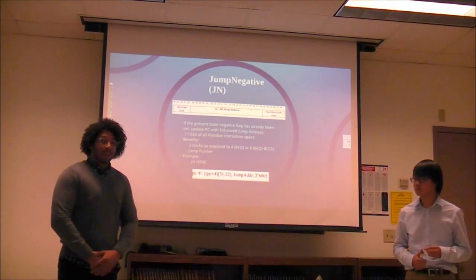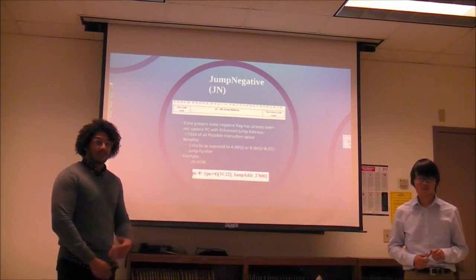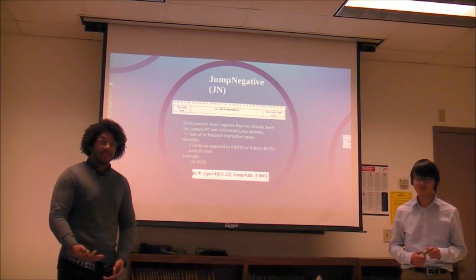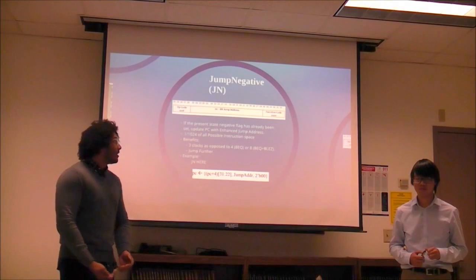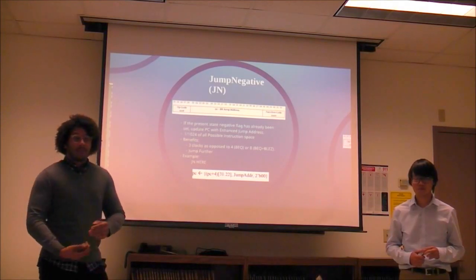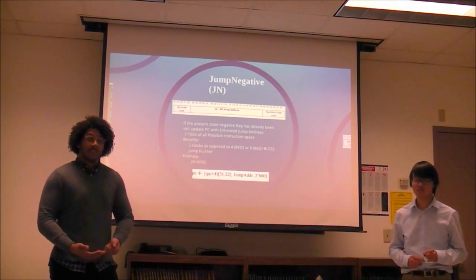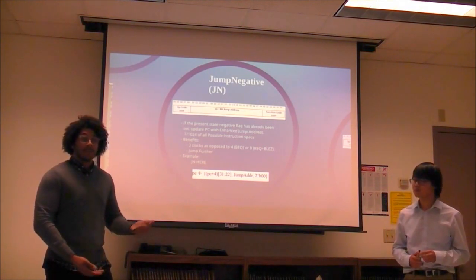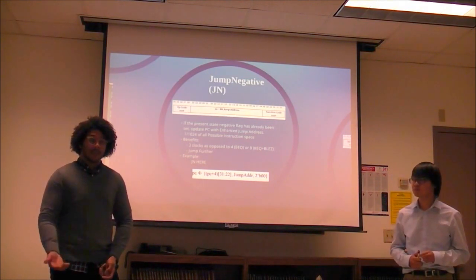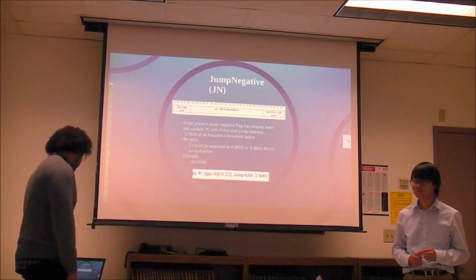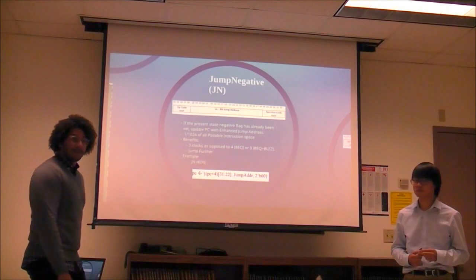Next is our jump if negative flag was set. This again is just a way of checking the validity of your numbers. This is beneficial because there is a way to check the negative flag using 2 instructions, but this could cost you 8 clock cycles, whereas this only gives you 3 clock cycles. And as well, you could jump further.